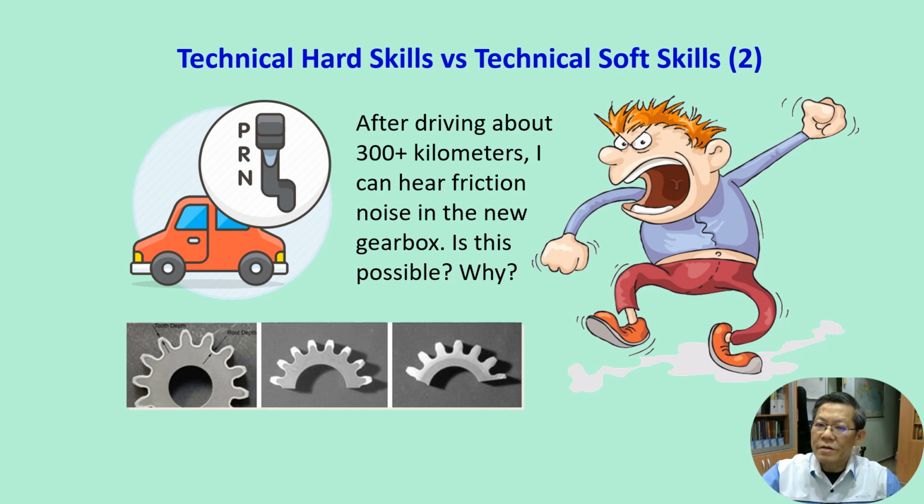The problem recurs constantly as the vendors have failed to study and correct the failure causes. I need to stress that quality control may pinpoint the defects, but the problem still need to go back to the basic to solve it forever. Technical soft skill know-how is used to reason a failure, suggest solution to remove the problem. The cause of the failure can be due to materials defect, poor contour hardening pattern on the gear teeth, which need to be studied and confirmed.